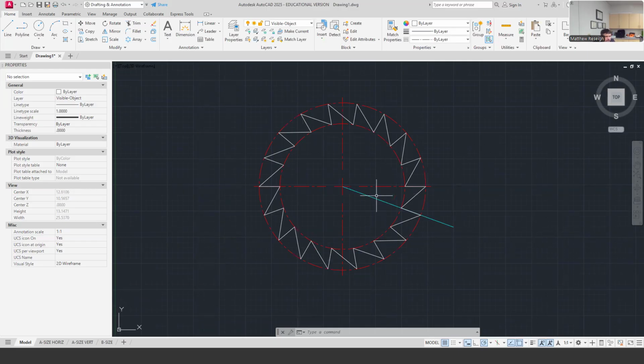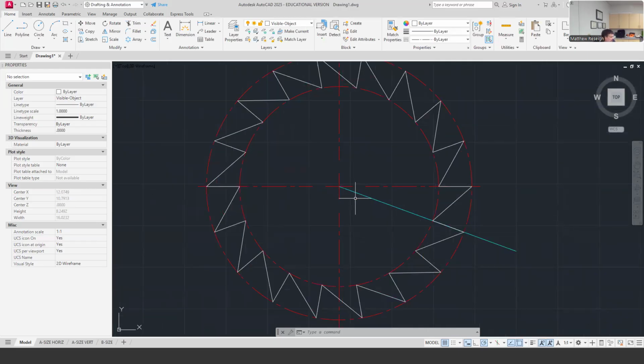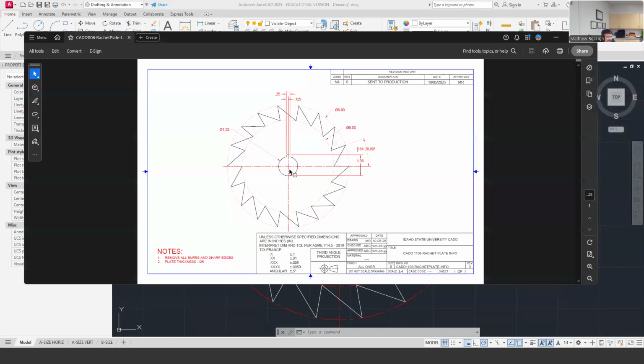And then I just need to do the keyway here. To me, I need to have that diameter to draw it, because even with the keyway dimensioning, I just don't have any other dimensions of how tall this key is to know which the diameter is. So I do feel like I need to know this to draw it. I'm going to draw that in first, and then I'll work on this keyway that looks to be a quarter, and it's an 1/8 inch off center, and then it extends up 1.36. Yeah, that's okay. 1.36. I'll leave it.